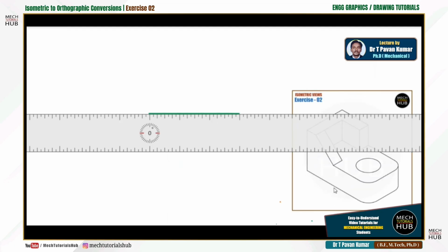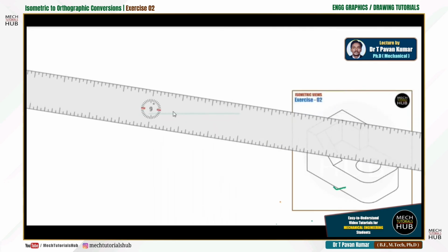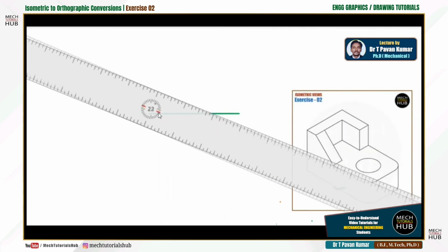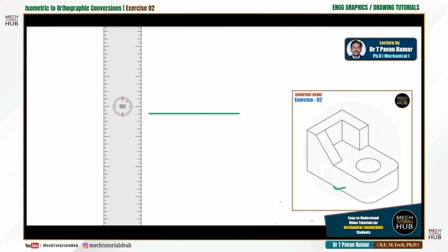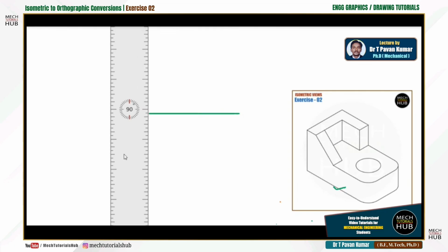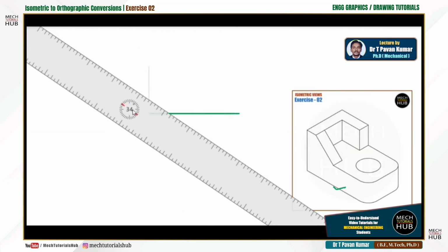Now this horizontal which I have drawn just now, followed by we'll consider this width as 20 mm. So at 20 mm height, let me draw one more parallel line. Let us consider that as 20, but that 20 is not continuous. After drawing the initial horizontal, let me draw the complete sketch with a 2H pencil and draw a vertical of this height. Conventionally I am representing this as the overall height.